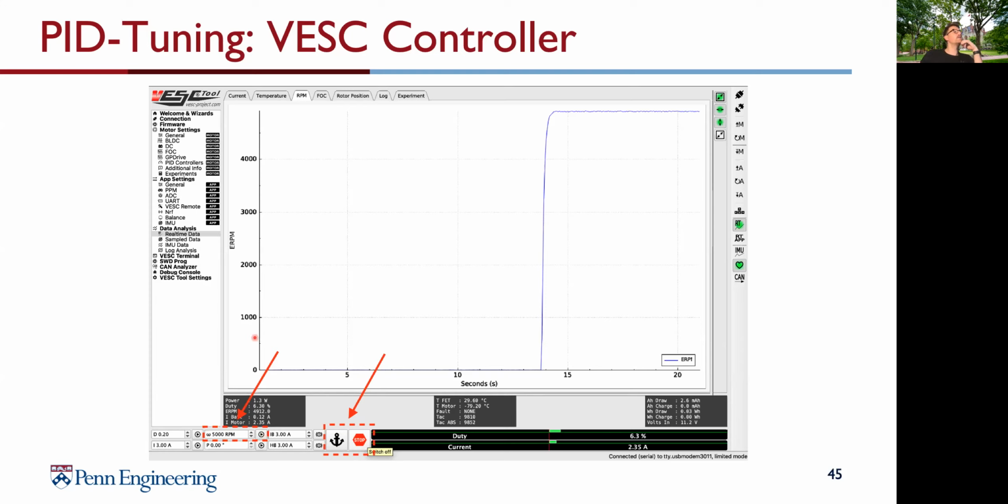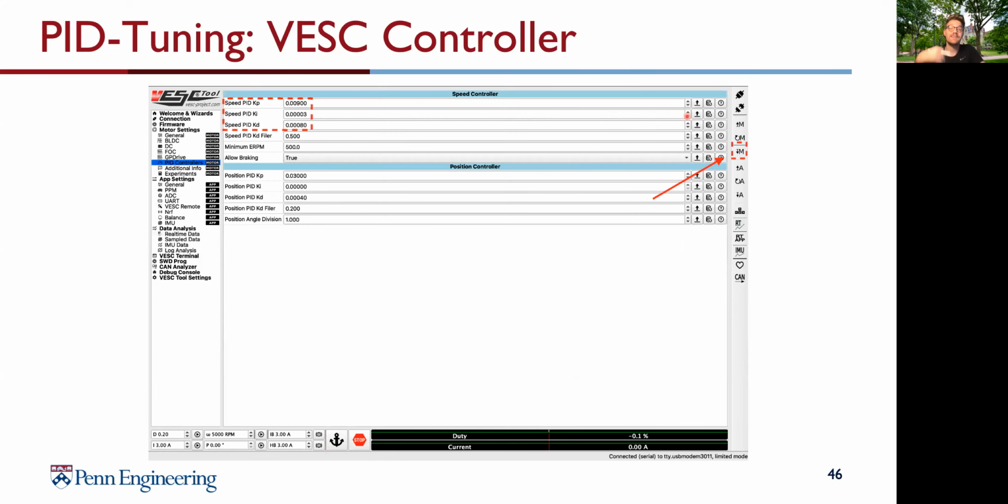And you can see here now the measurement of the step response. So here's the measurement. Our motor is not doing anything. We have the step response, which is really high, and then goes up to 5,000. And we can see the behavior of the engine afterwards. You want to look for a clean step response that has a quick rise time and zero to very little steady state error.